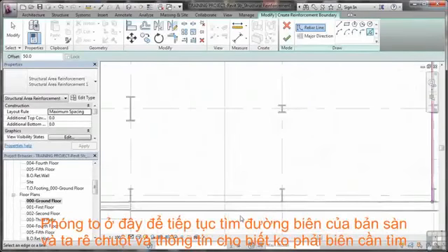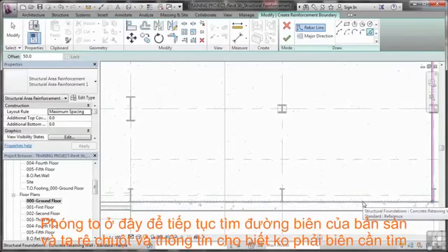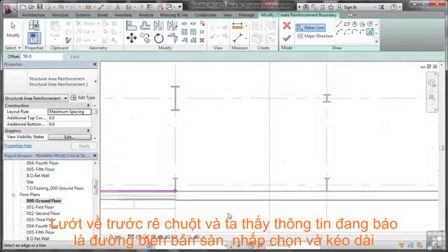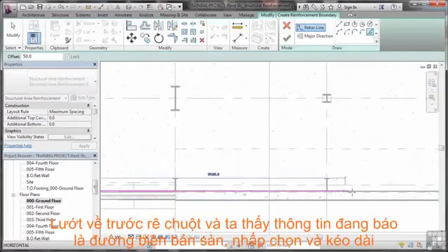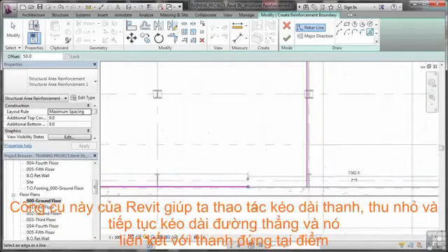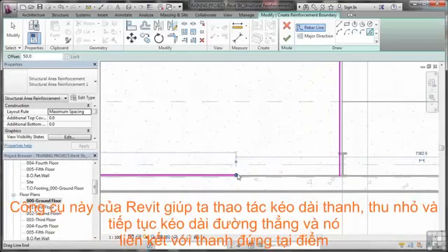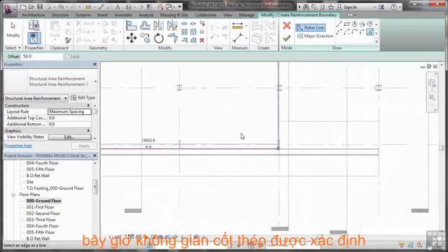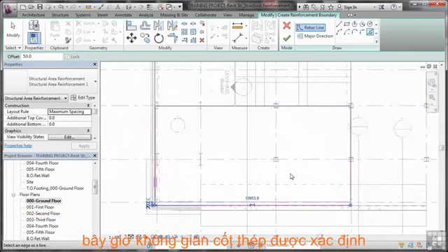And if I zoom in here now, I want to get the slab edge again. You might possibly get structural foundation on the retaining wall because that is also there. So you might need to move along a little bit. There's the foundation slab there, like so. The trick there would be, I would actually just take this line along horizontally. Because the good thing about the Revit tools is as I pan across now, if I zoom in a bit, I can click on the end of that line there, and as I drag, the drawing tools allow me to snap to that endpoint. So that's now a closed loop ready for my area reinforcement.